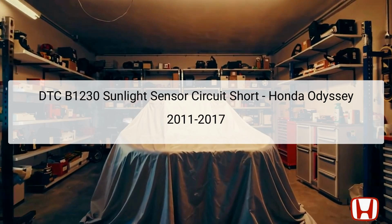DTC B1230 indicates an issue with the sunlight sensor circuit, specifically designed to control functions associated with the vehicle's climate control system. The sunlight sensor itself plays a crucial role in monitoring ambient light conditions to effectively regulate temperature and airflow within the vehicle. This component is typically located near the windshield on the dashboard, where it has direct exposure to sunlight. When the system detects a short circuit in this sensor circuit, it triggers the DTC, warning the driver